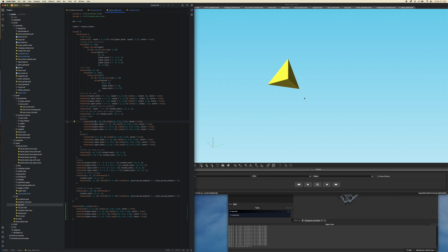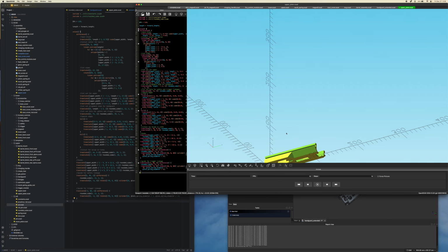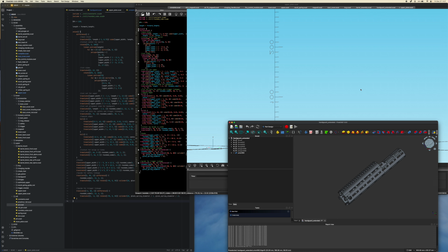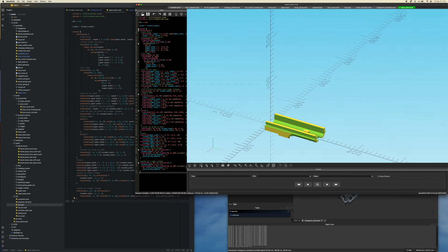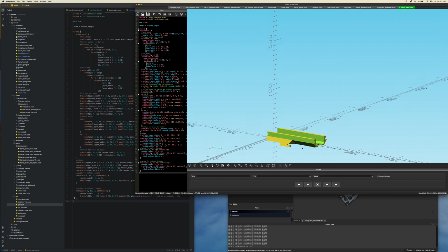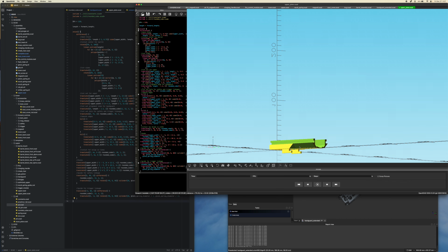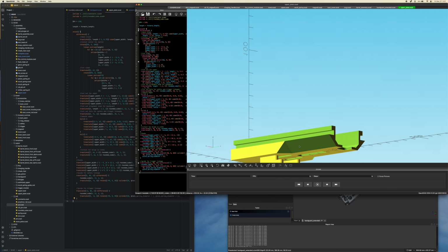So you want to generally be careful with the hull. It works fine in OpenSCAD, but again, it is a little glitchy sometimes in OpenCascade. It's fine if you're just doing 3D printing, but if you're going to do any CNC, you need to have those step files, and you're going to have to be a bit more careful with the code you write.